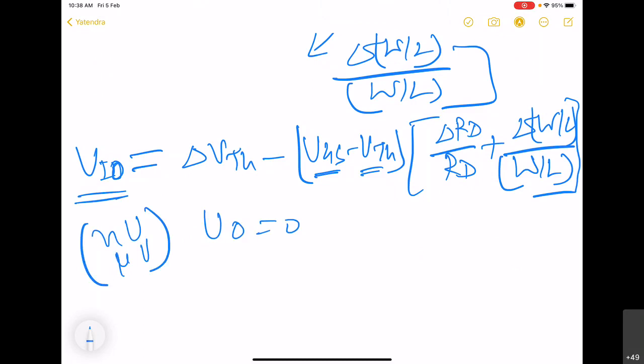But keep in mind that this will get amplified, and on the output side, the usual offset that you will see will be significantly larger compared with the input. So although on the input side this quantity is very small, its effect on the output side will be non-negligible usually. So one has to take care of this in some of the scenarios.